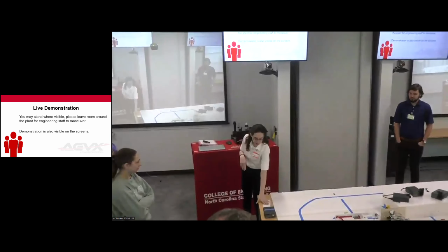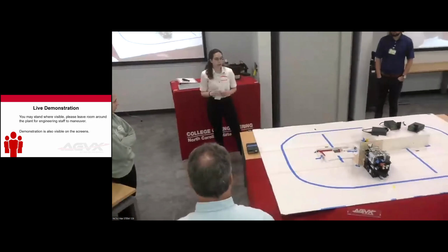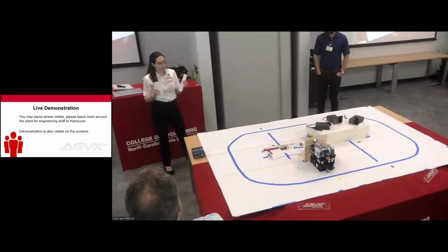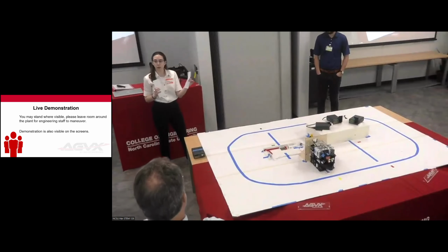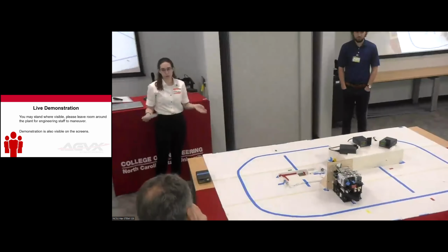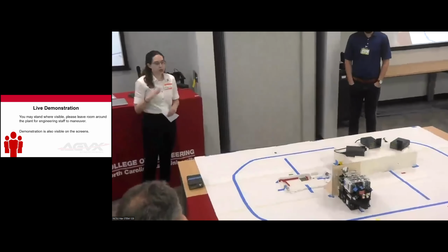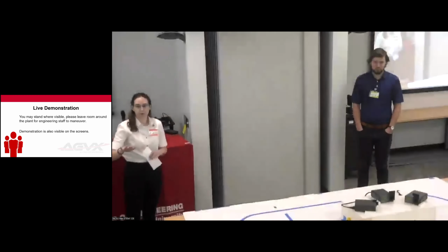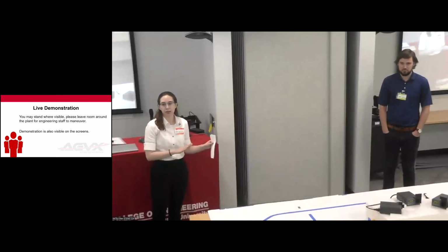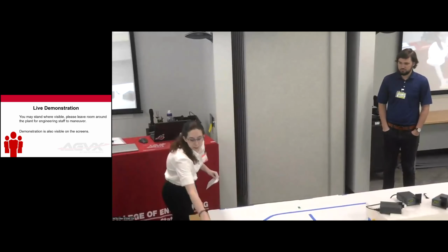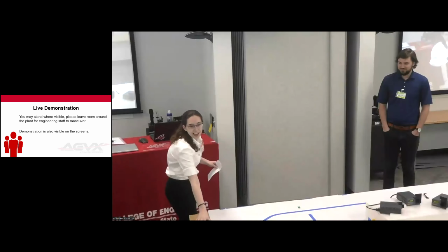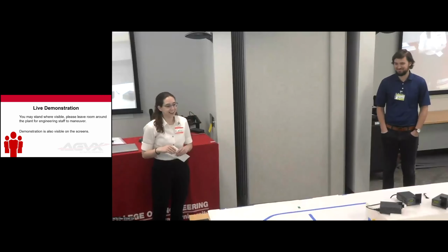The first drive around, we're going to let it roll over some different line breaks. We have a 2-inch line, so it will drive over this one and continue moving normally. On the 3-inch line, it will stop motion because that was our requirement, to stop at a 3-inch line. It will signal that it's lost and send a page. Then we'll drive around again and do some object detection, making sure that it sees the objects as we drive around. I'm going to use this because it seems to be the best object that we have that will not get tipped over accidentally.